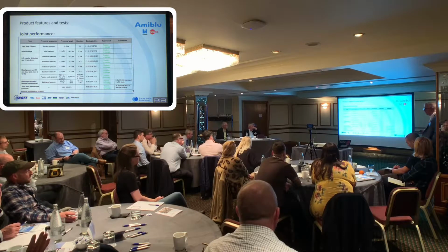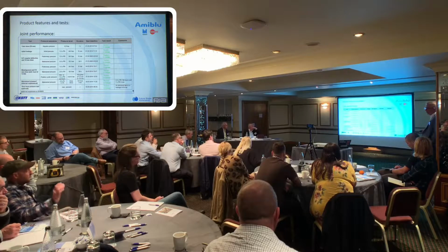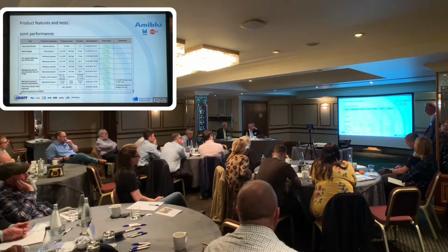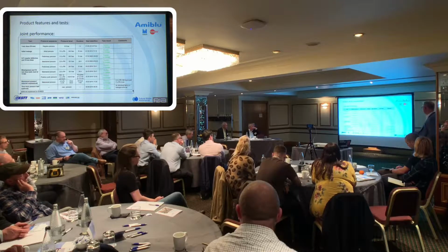There's a big difference with other pipe materials. I know for concrete pipes, for example, they test at half a bar in the joint, with gravity. We test at 2 bars.